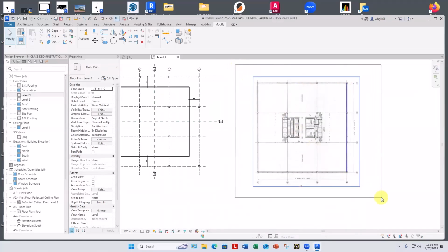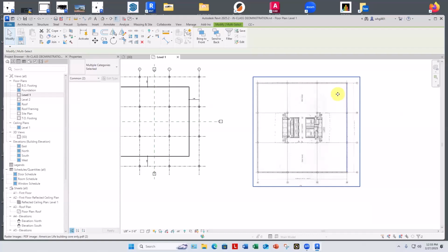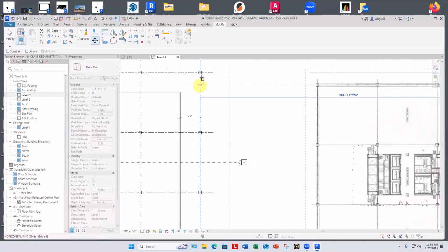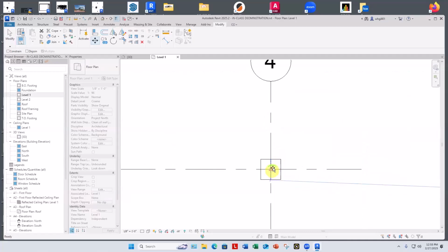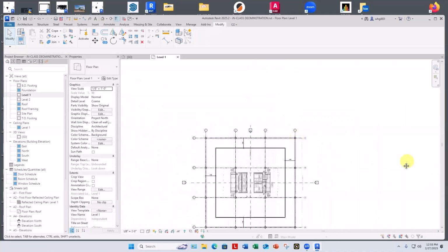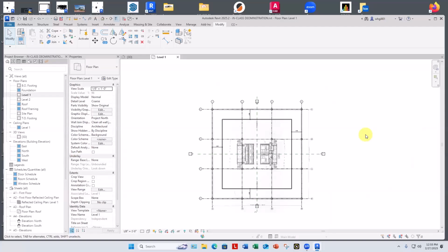So I'm going to window both of these again, PDF and line, and use the move tool, MV. You'll see that flash up across the screen sometimes. And we're going to pick the endpoint of that line. It's the only thing up there, the red square to say endpoint. From there I move both of those together over to this intersection. Right now, this is the center of each of those two little lines. It's the intersection of the whatever, but you get the point right there that highlights. And we can zoom out and we can see that that's exactly in position there.